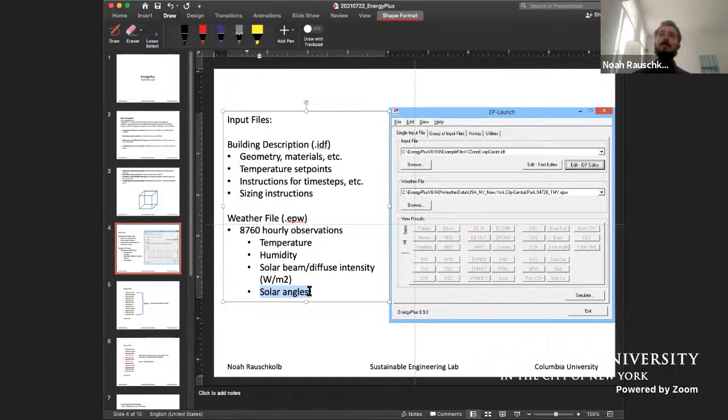So the reason I point this out is that if you're trying to bring in a weather file, or trying to make your own weather file to plug into EnergyPlus, and you want to just take something off of, say, the ISD system, which some of you might know about, then there's actually some serious steps to making that file work with EnergyPlus. Hassan has a question.